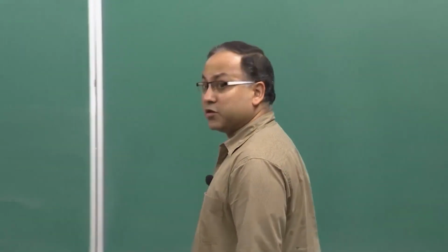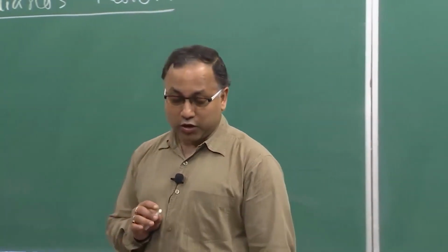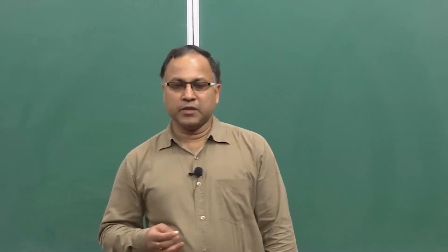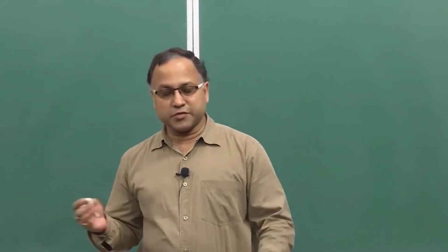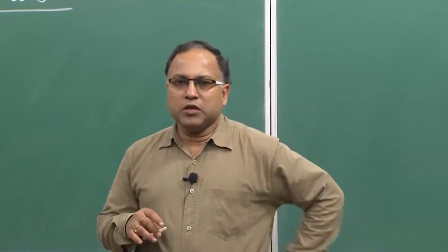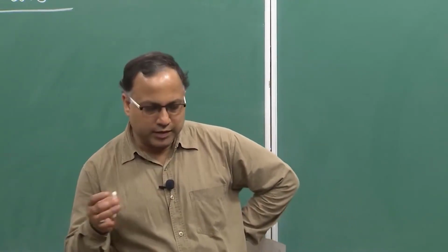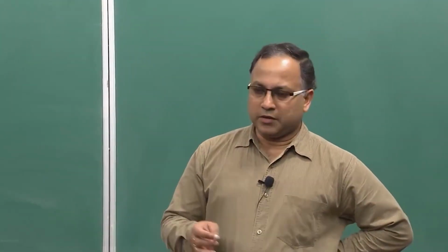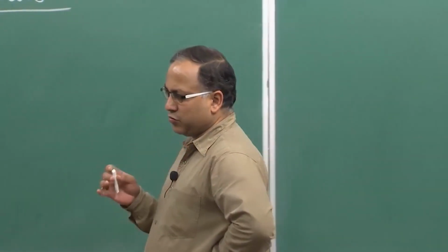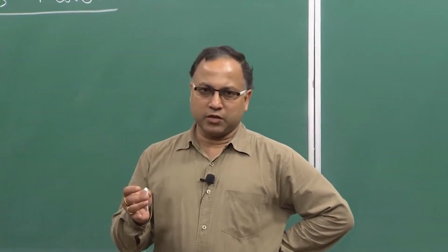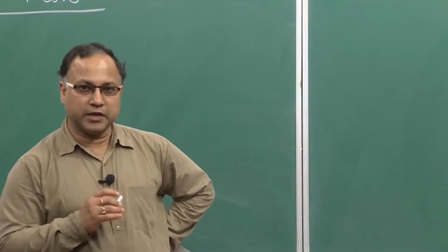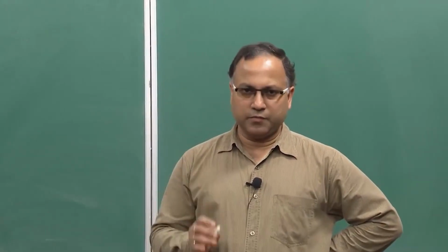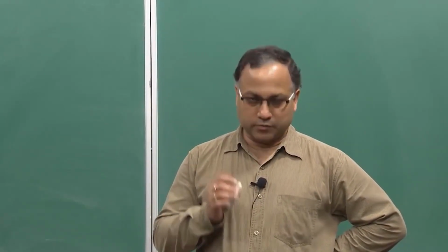Welcome back to the course Mechanics of Solids. In the last lecture, if you recall, we talked about the potential energy, complementary energy, and the conservative system, and based on that we derived one relation, that is del U star by del Pi is equal to delta I. That means, if you take the partial derivative of the complementary energy with respect to a particular force Pi, that will give you the deformation or the deflection along the line of action of that load Pi.